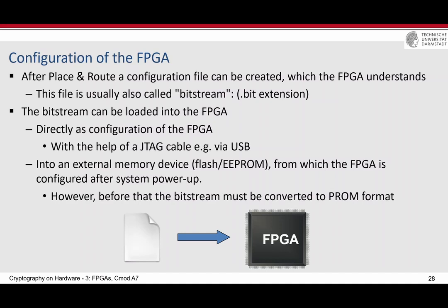And one more thing: usually on these boards with an SRAM-based FPGA, there is a flash or EEPROM, which is non-volatile, and you need to configure it. Then after power up, this configures the FPGA automatically. This is usually done by the developers of the boards, which are developed as a toolkit or any other device. For example, if you build a Cisco router, after power up it should work, and you should not have to configure it. It will be configured automatically by a non-volatile memory on the chip.